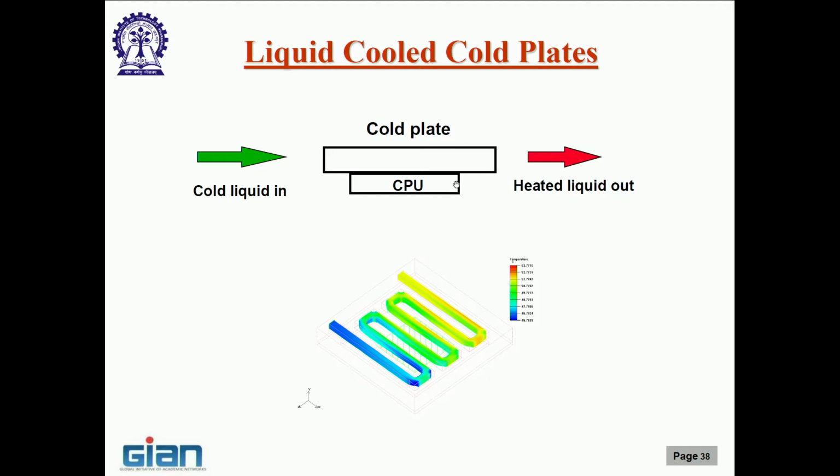And in flow boiling, the heat transfer coefficients are much higher compared to single phase, but so is the pressure drop. Pressure drop is also much higher compared to single phase, right. So we again have to do a trade-off and see whether it is worth going to two phase heat transfer at a lower flow rate versus single phase heat transfer at a higher flow rate, and see how the heat transfer coefficients and effective thermal resistances compare.